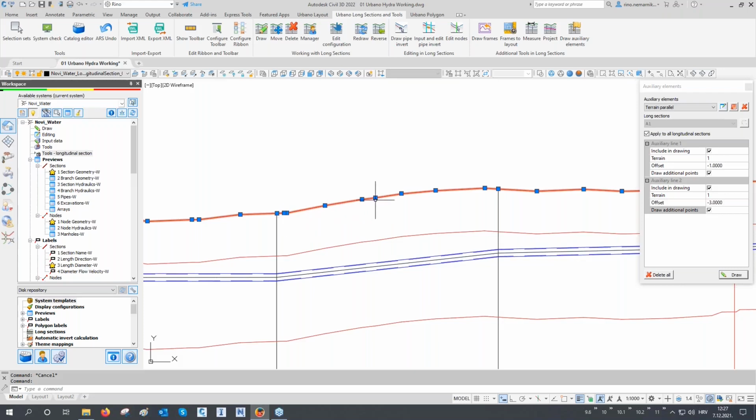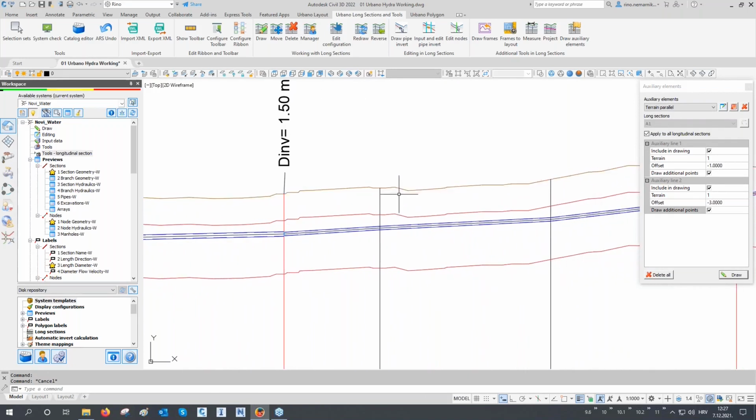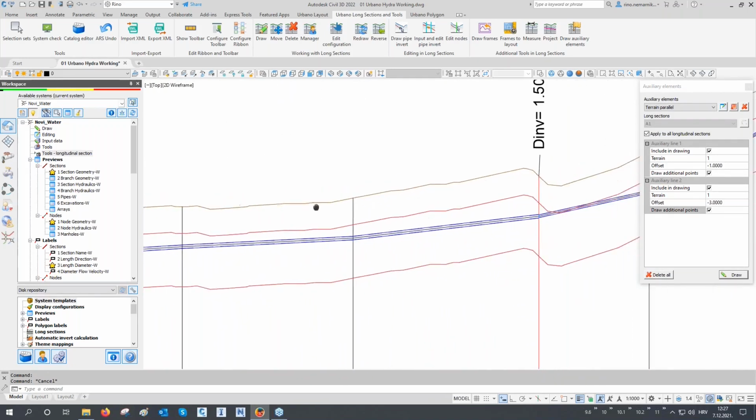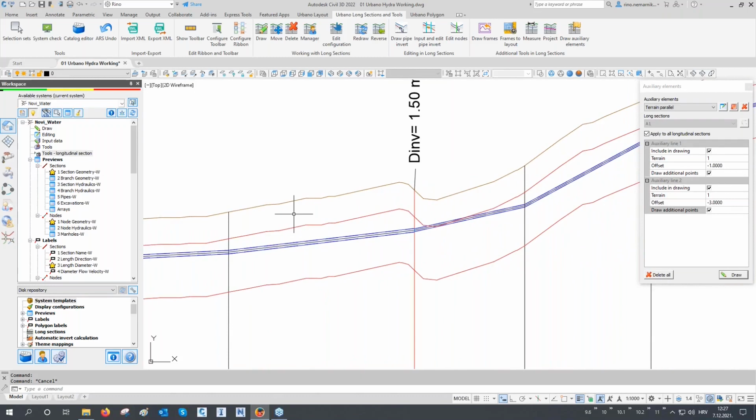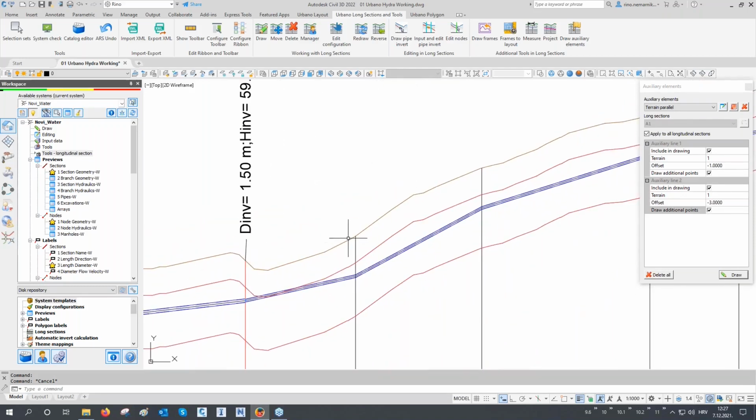Of course, if you notice that some points are not surveyed correctly, you can also delete some of those additional points. But it's really important to have them because later on we will also calculate the trenches and the excavation volumes. So it's not the same if, for example, this line here is straight or if it goes up and down, because with the volume calculation that we will run later, you will basically not get the right excavation volumes.